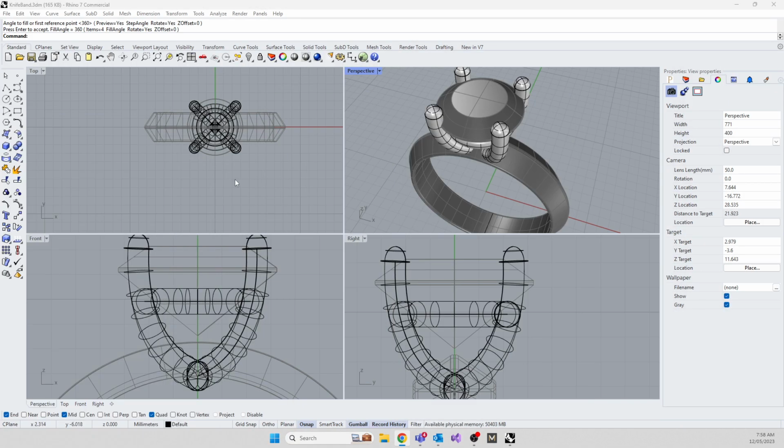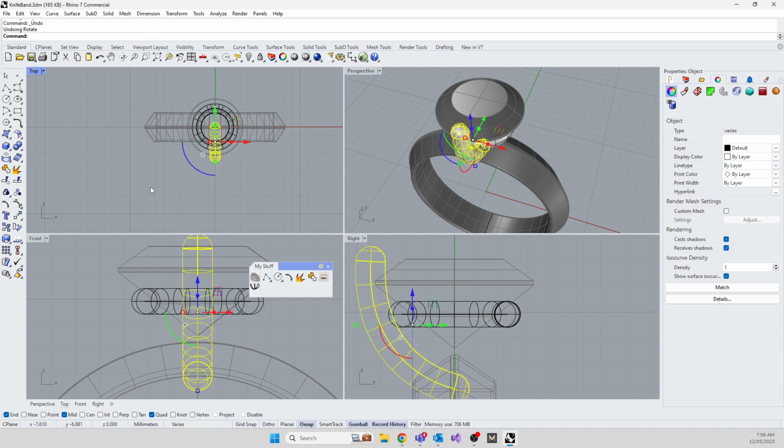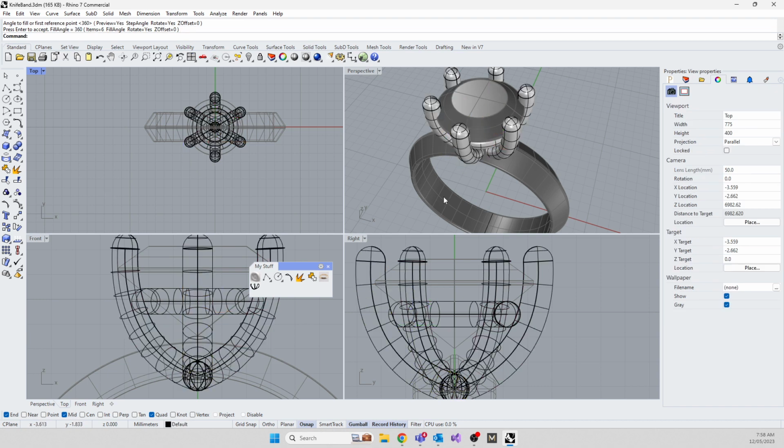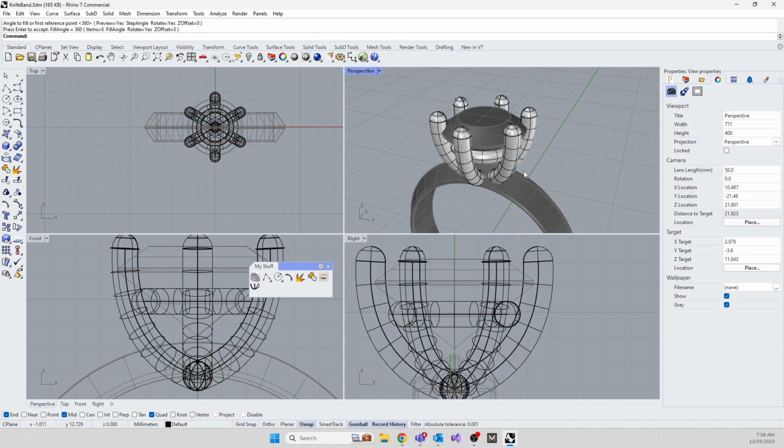You could have made it at any angle. So this one you might want to save out as a 4-claw collet. Then you come back in and rotate it back, and you also make a 6-claw collet. So you go Control Z, Control Z, oopsie, Control Z, and from here you do an array polar around 0 with 6, and you've got a 6-claw collet, and then save that out. Then, using the constructs you use with history, create a 4-claw and a 3-claw and a 2-claw, and when you need them, you just pull them out at high speed.